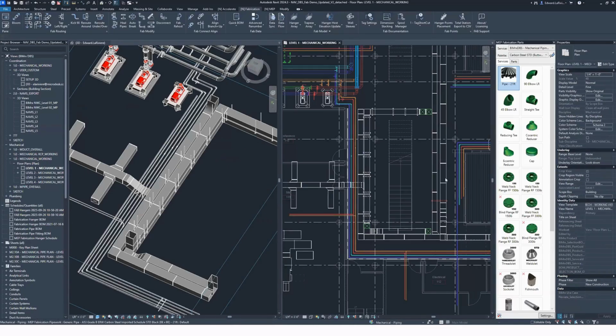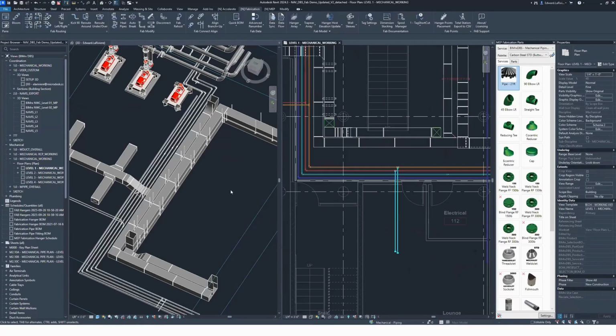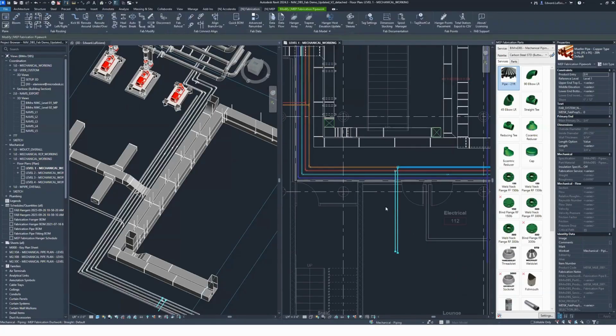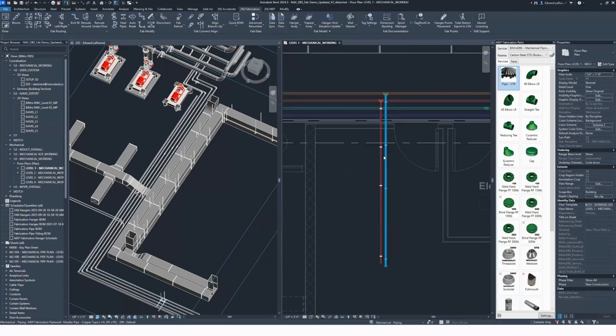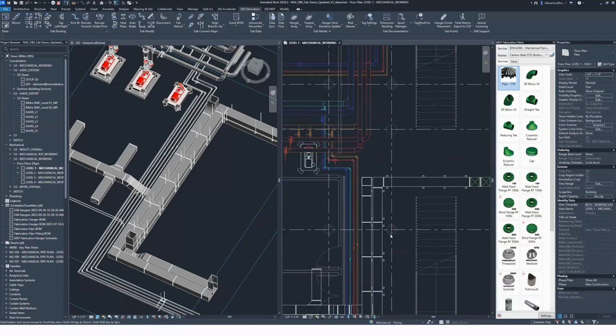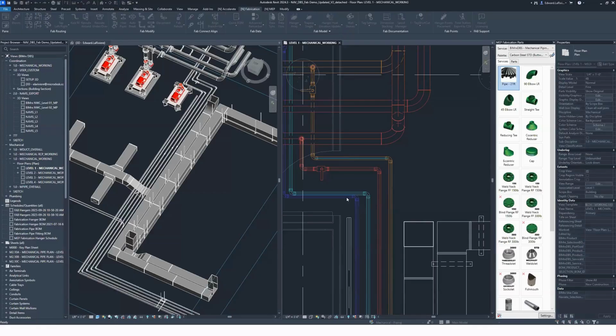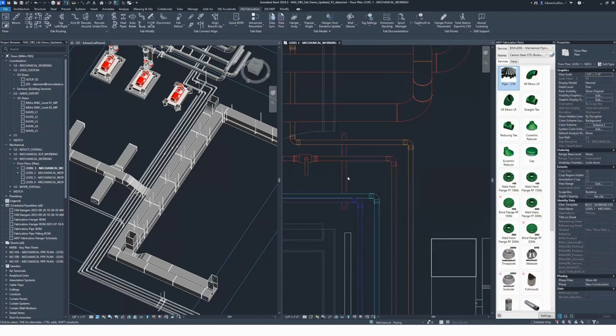Jumping up this way, maybe I want to use some of those other tools. Those base hanger tools we saw here, just placing down a single run of trapezes. If we do that same tool on those pipes, because we told that hanger to place clevis, we'll see some clevises showing up on those pipes. If we want to do a pipe trapeze, go find a spot you'd like to do that, and do something maybe like trapeze single, to choose a start, an end, and an OK, and have it stretch across all those elements for us.